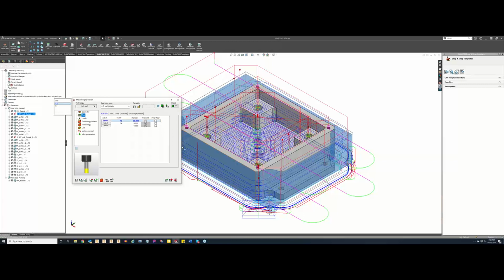There are going to be instances where you're going to want a higher tool rigidity that comes with larger diameters. For this in particular, all we're really focused on is a small radius in those 4 corners. But if we had some heavy roughing everywhere else, you probably want to go with a beefier tool and step it down. Also, larger tools mean the cutting angle is going to be larger, which ultimately results in a larger step over.